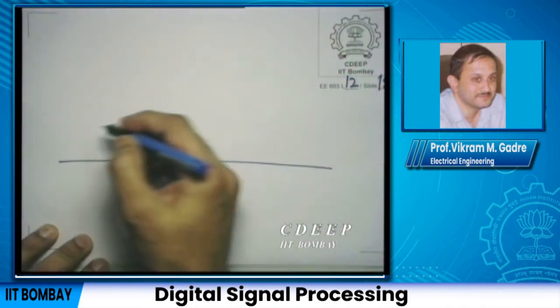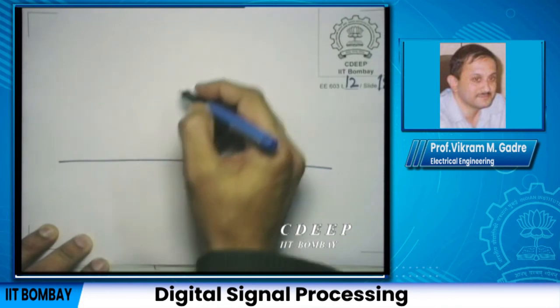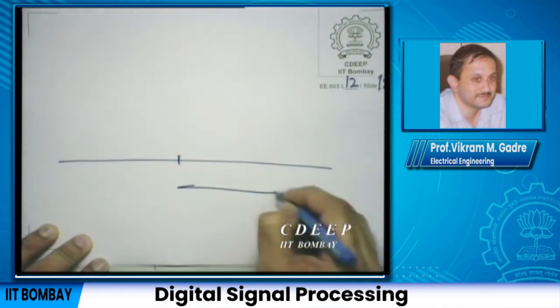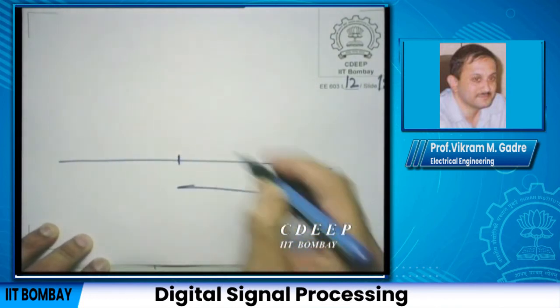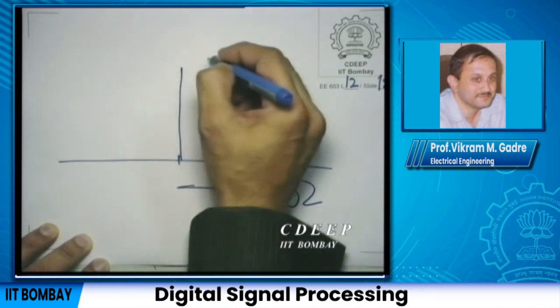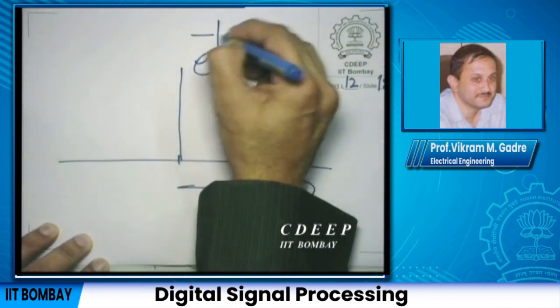Similarly, finite energy is broader than band limited. You can have a finite energy signal which is not band limited, a signal whose spectrum extends all over the frequency axis. Take for example the signal which has a spectrum which decays like this. Let this be the frequency domain, and you have the spectrum e raised to the power minus mod omega.